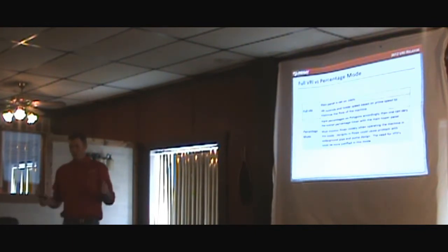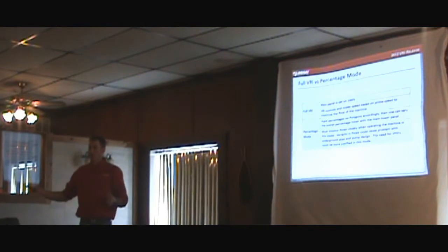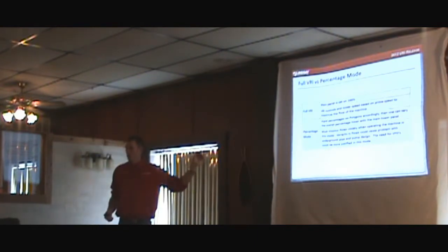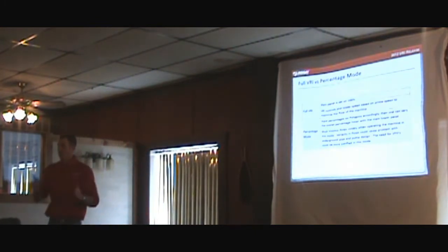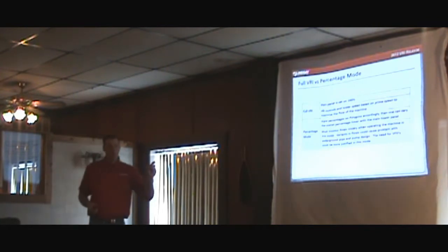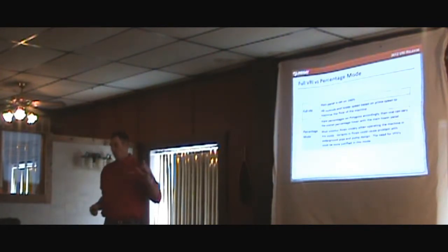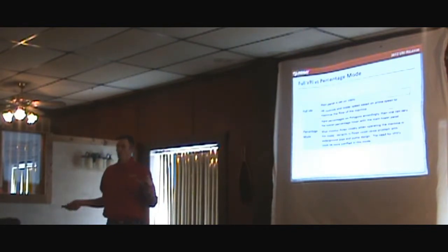If you only have VRI on, say, 3 or 5 spans, which we can do, you don't have to put it on the full 7 towers. You have to run it in percentage mode. Okay? What I'm about to explain, you can't run it unless you have nodes on the entire machine and valves on the entire machine. Are we good so far? Okay. So full VRI. In full VRI, we control the travel speed of the pivot. You do not input percentages, you input rates.